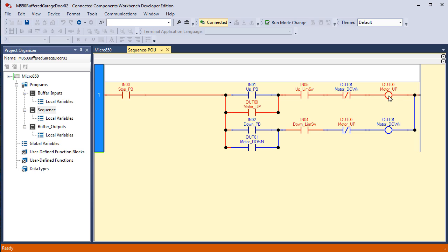I can put a meter on the terminal, see if there's voltage going out. I can go to the other end of the wire at the starter coil, put a meter there and see if there's voltage there, and on and on and on, all the way to the motor. Then, of course, you can test the motor if everything checks out all the way up to the motor, but the motor's still not moving.